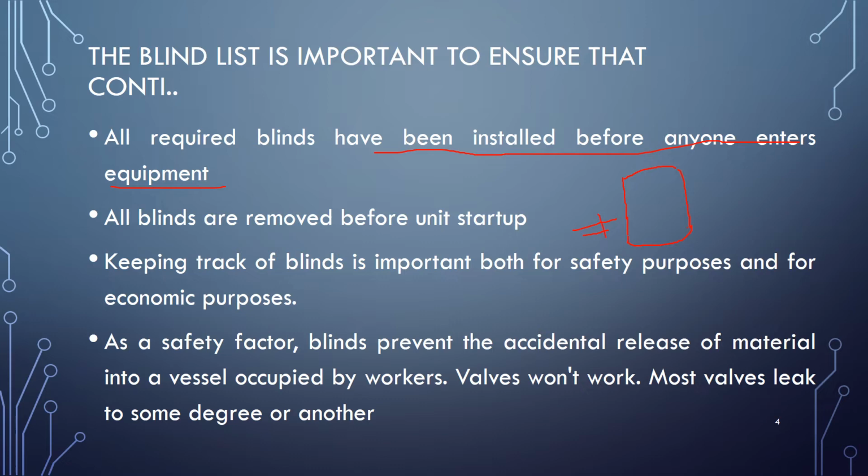they have to be very careful that no blind is there before we allow the raw material or purging fluid. So all the blinds should be removed. For example, if you have one valve here, I am putting number 1. Before the valve as well as after the valve, they put a blind. That is called positive isolation. If I am going to allow the fluid inside, I have to make sure there is no blind, so I have to remove this blind as well as the other blind. Based on that, I can supply the purge fluid inside the tank, column or reactor, whatever it may be.